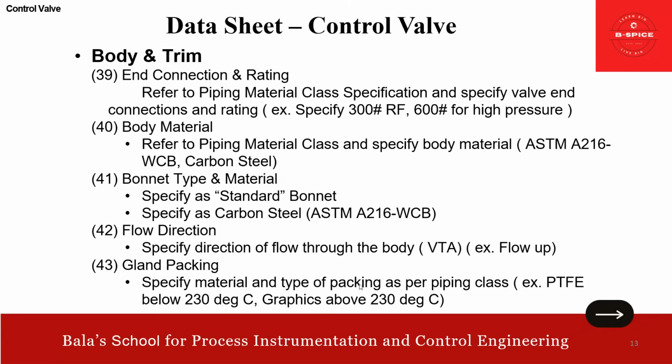Specify material and type of packing as per the piping class. In this case, we can use PTFE, which is Teflon, if the temperature is below 230 degrees centigrade. If it is above 230 degrees, we always go with graphite. Friends, I think gland packing is also clear.